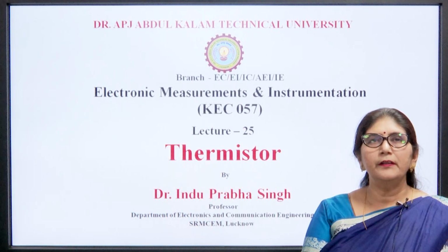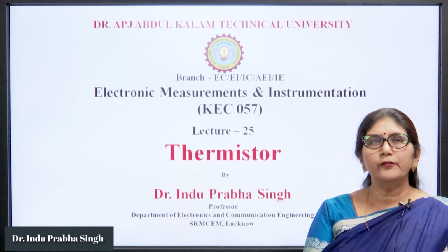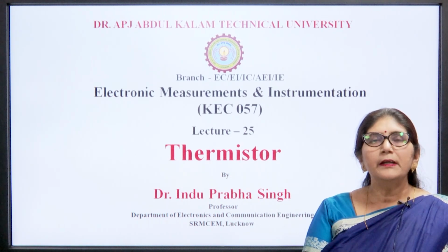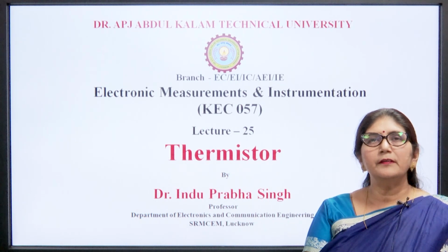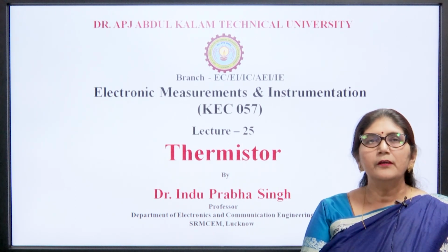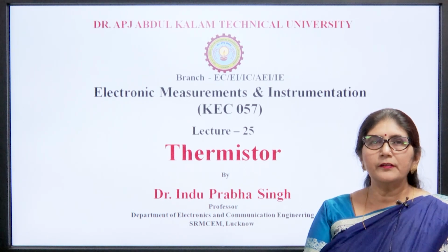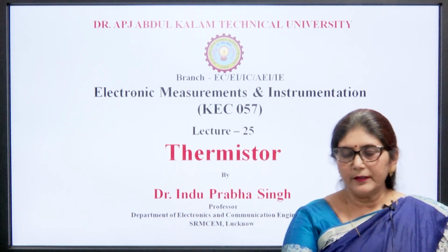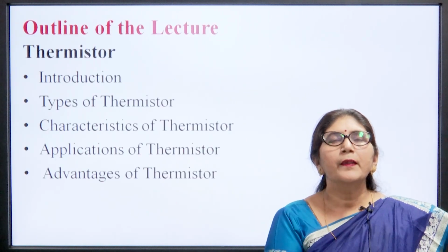Welcome you all to the 25th lecture of Electronic Measurements and Instrumentation. In this lecture, I will discuss a transducer which converts change in temperature into change in resistance, that is the thermistor. So, in this lecture, I will discuss the thermistor, that is the thermal sensitive resistance.